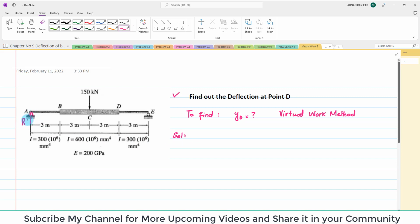If I remove the supports, the reaction force at point A will be RA and the reaction force at point E will be RE. Now you can apply the equilibrium conditions: the sum of all forces along the y direction must be equal to 0, with upward force taken as positive. The second condition is that the sum of all moments about any point must be equal to 0. You can use these two equations to find the reaction forces at points A and E.